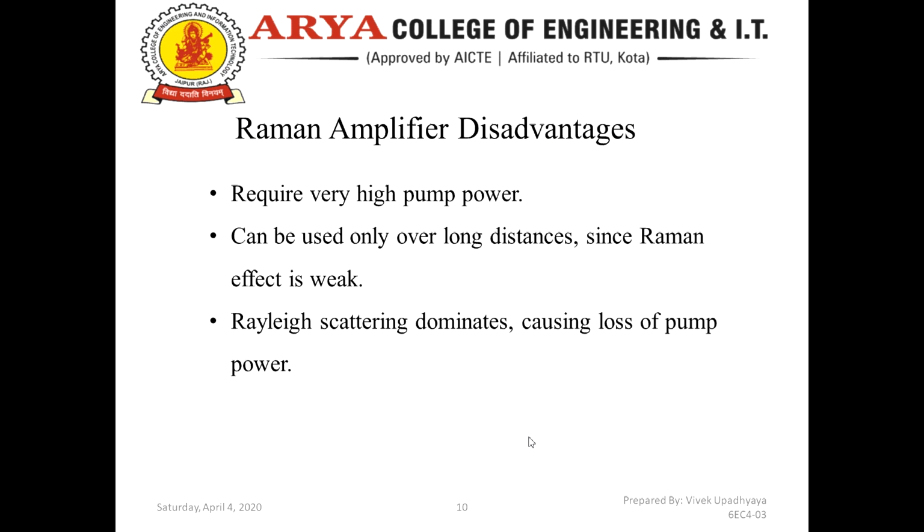It requires a high pump power; it cannot be sustained with low pump power. Second, it can be used only over long distances, since the Raman effect is very weak. Then Rayleigh scattering dominates here, causing a loss of pump power.